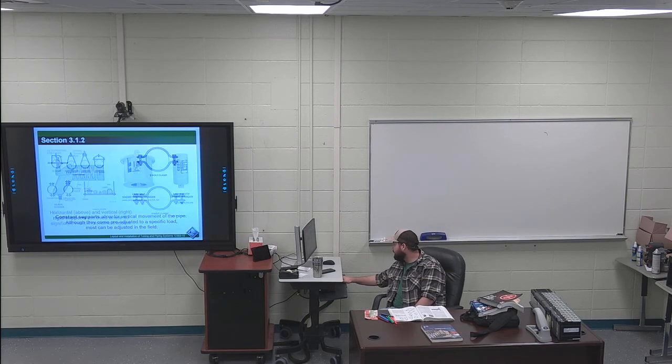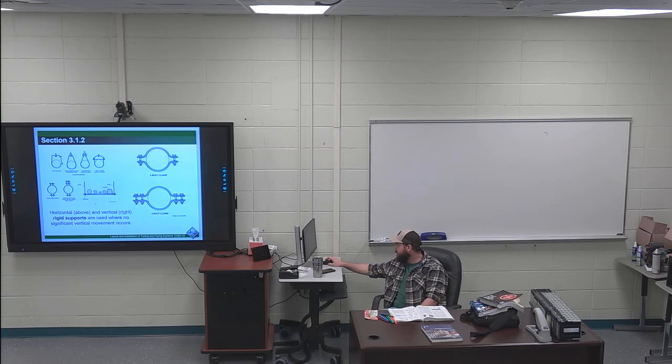Rigid hangers and supports. You've got different types of hangers that can be hung from all thread and pipe clamps or beam clamps hung from the ceiling. Used a lot. You'll see these a lot for fire systems. So you have rigid supports. Nothing highlighted in those, but you can see there's a bunch of different types of clamps with different amounts of bolts depending on what you're doing. Snubbers, again, you should know what a snubber is. I think we covered them in the last chapter.